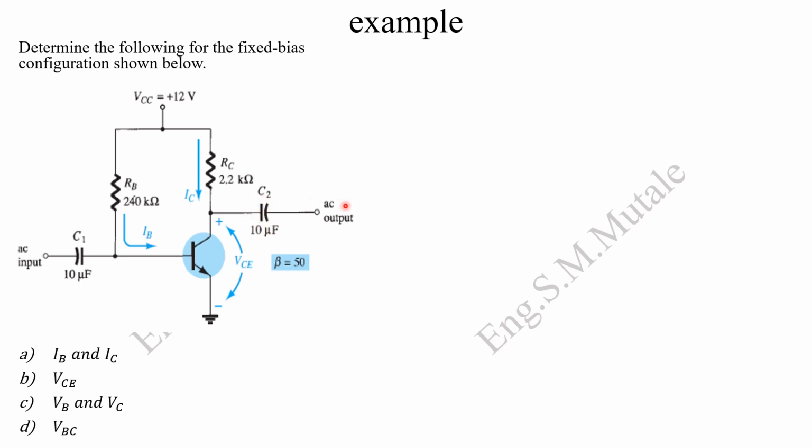So this part will be out. Even here, as it comes there, it will go there, but this side, it will not go because of that capacitor seeing an open circuit. So all the capacitors, you're not going to be using them when you're doing DC biasing, because they are just open circuits. DC doesn't see a capacitor. When it looks at a capacitor, it looks at a window actually.